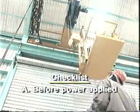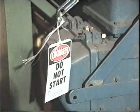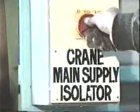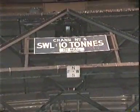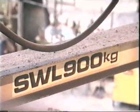Before power has been applied to your crane, you should firstly check to see that the crane is not tagged out of service, and that the main isolating switch is off. Check that the safe working load notice is displayed on the crane. If this notice has been removed or defaced, then it should be immediately replaced.